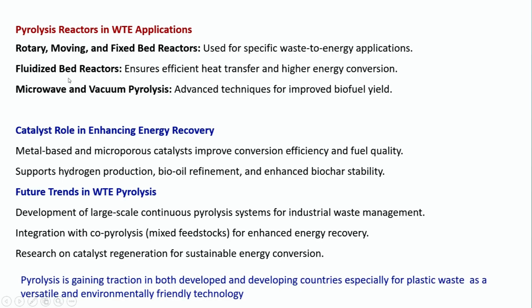And then you may have fluidized bed reactors, which ensure efficient heat transfer and higher energy conversions. And if you want to achieve higher temperature or energy conversion, definitely you have to use microwave and vacuum pyrolysis. These are all advanced techniques for improved biofuel yield.